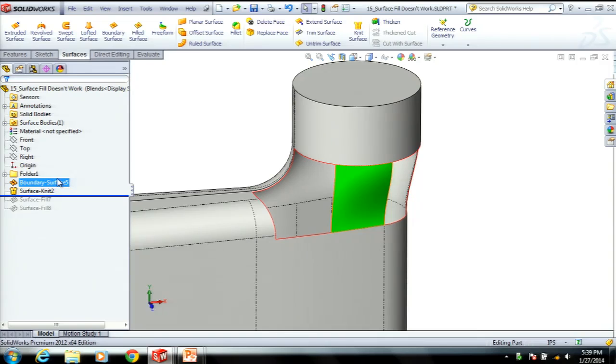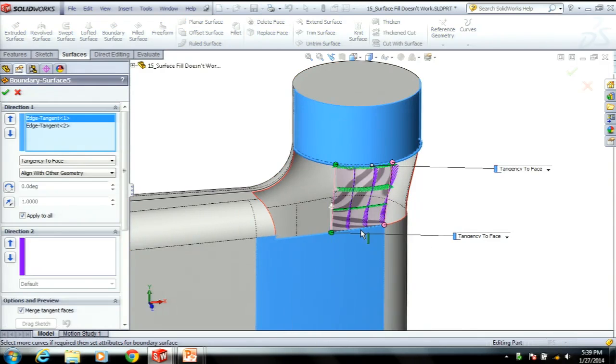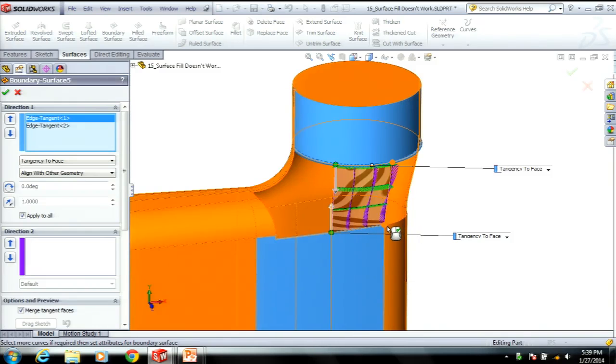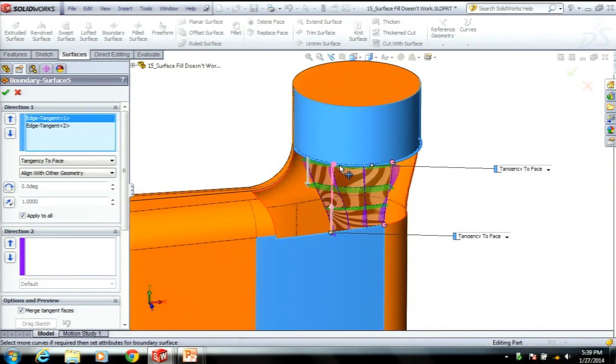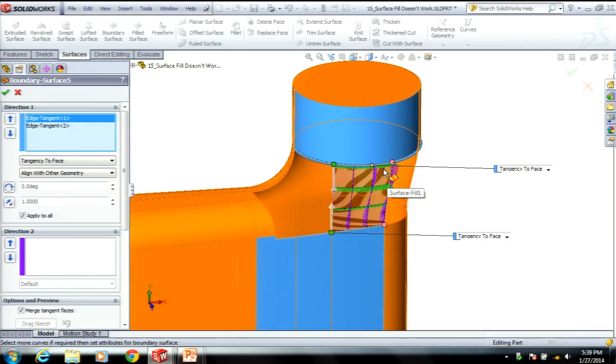The literature says it's snap the points, but yes, it will snap to splits along the edge here, but there's really no kind of point. I can't say I would like it to be vertical between these two, or I can't say I would like it to be a half inch from this edge. I believe it uses percentages along the edge to position them when you have rebuilds.